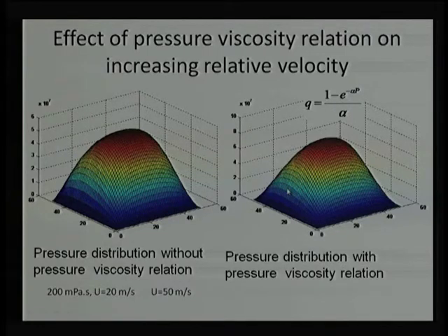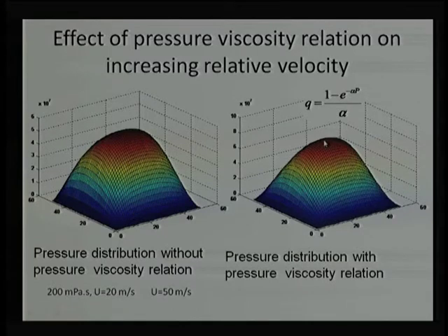First, the cause is a pressure increase, deformation will occur because of that, and because of the deformation film thickness will increase, and because of the increase in film thickness pressure will decrease. So, there will be self adjustment. What we are predicting just because of the viscosity, there is a possibility that when we account for deformation, pressure again will come down to some level.